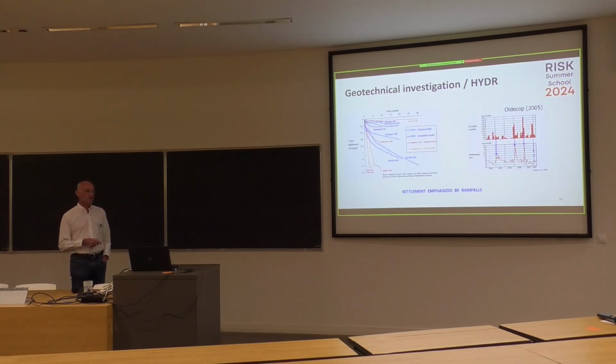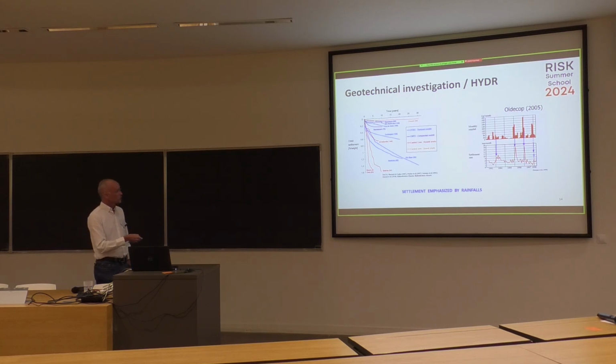Okay, some observations from the field to introduce the interaction between the rockfill and the water. What we observed when you monitor a dam is that the settlement of a dam is increasing with time. It means a settlement at the crest of about 1 to 2 meters for a dam of 200 meters high.